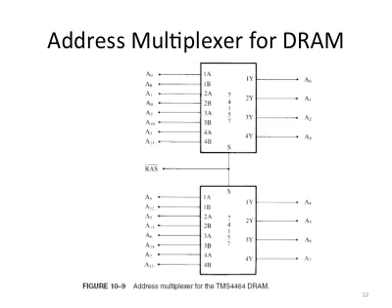Sometimes these multiplexers are used for DRAM access. What we see here is two 2-to-1 multiplexers. This one, as you can see, has two channels, A and B, with 8 inputs and 4 outputs. Depending on the control signal here, this chip will select one of these two channels, either A or B.